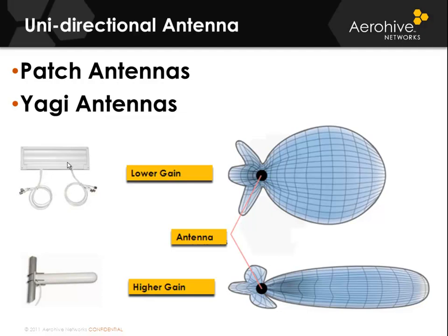So when you're looking at using this type of antenna, you want to make sure that the antenna is focused towards the intended clients. I've seen internal antenna used that would be a patch pattern focusing upwards because someone has laid them down on the ceiling tile with the bottom of the access point facing the floor. Please remember to face the coverage towards the clients when using these, and either mount them on the ceiling facing down, turn them over face down inside the tile, or mount them on appropriate walls or poles facing in the direction which you wish to have coverage.